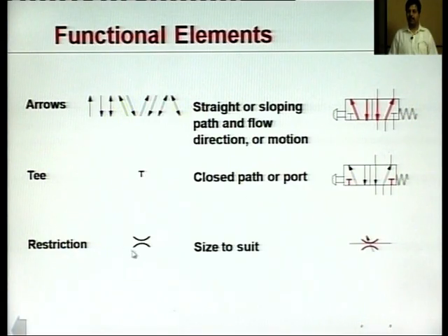We also come across these type of symbols. These are restrictions. It shows that the wall or the pipe from where the fluid is flowing, and which is marked by this type of symbol, is a restriction which is causing the fluid to move through this restriction. And in case it is guarded by a slant arrow, it shows that this particular combination is an adjustable flow control valve.